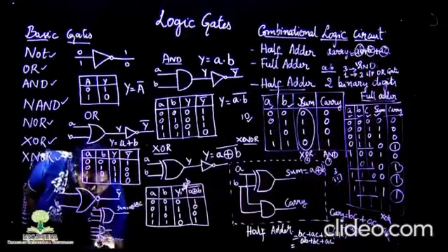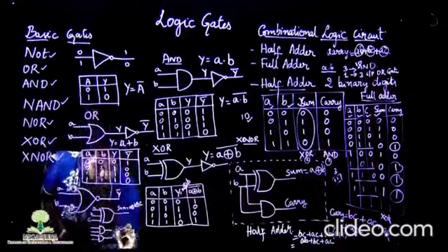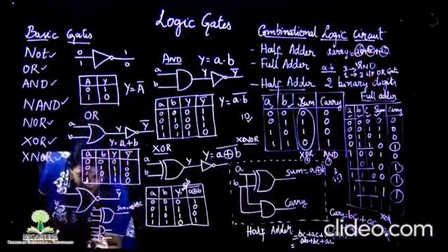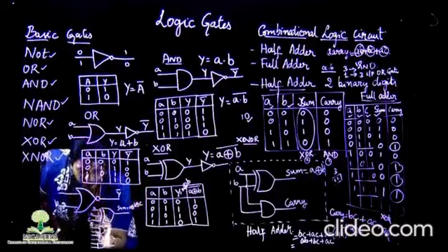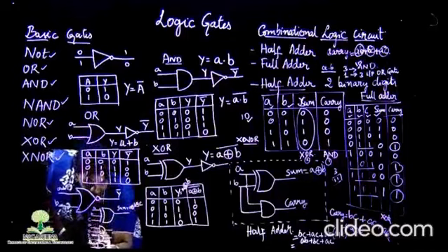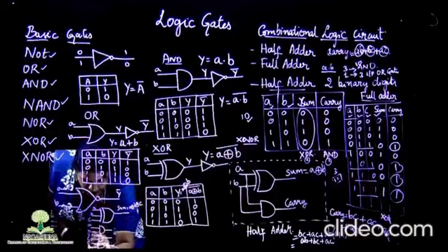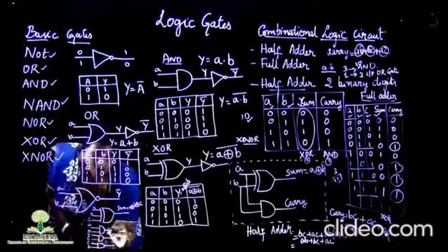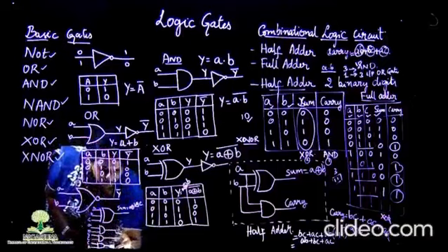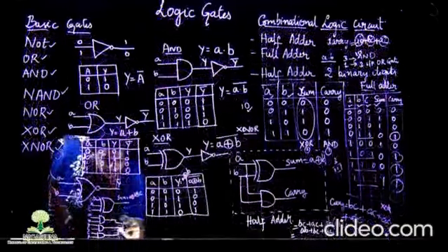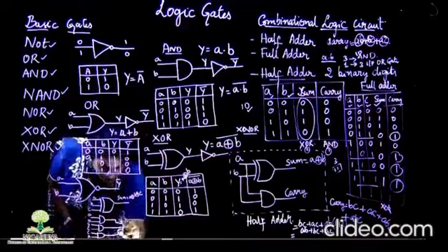B and C, and A and C. You can directly take these as inputs, or else you can represent them here also as B, C and C, A. So, these are the inputs, and combined with that, the OR operation is done with the 3-input OR gate.